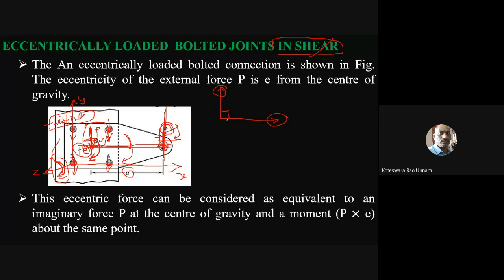That is nothing but a force. You can take this one as one force and this as one other force. If I take this as Px and this one as Py, then our resultant load PR is nothing but square root of Px square plus Py square. But that is as long as it is 90 degrees.